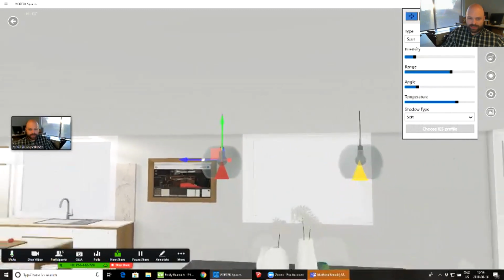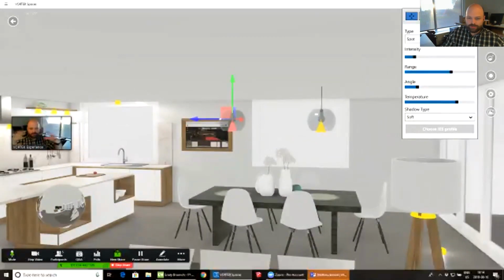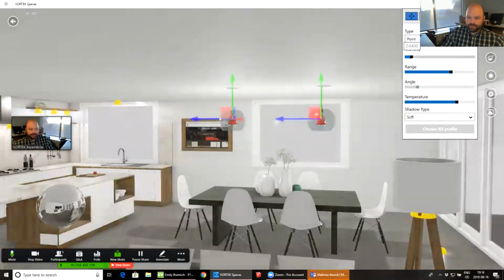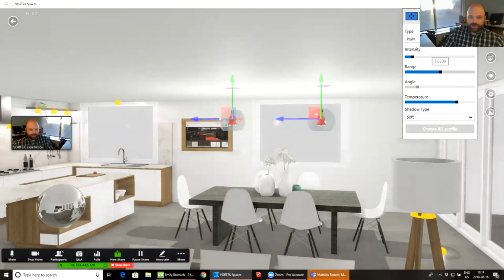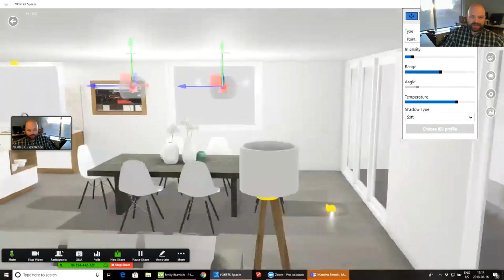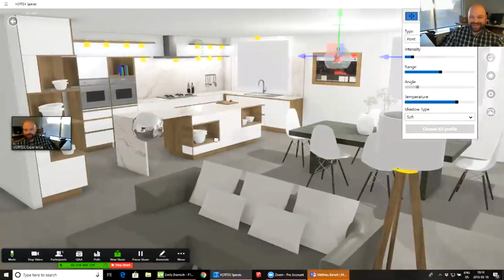Again, since that type of light should go all around, I'll switch those 2 lights to a point light. Like that, point light. And again, I'll probably play with the range. With the range, it's always better if you try to go a little bit far away when you set up your lights, especially when it's main lights like that, because sometimes it might look very good from very close, but you're kind of scrapping everything you've done on the other side.